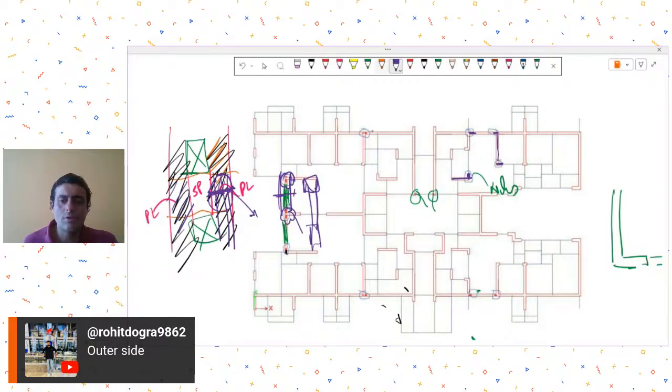Okay, so try that. And then over here, if these nibs are failing where the beam is connected, these generally fail due to the load transfer that happens from these beams to these nibs. So check what type of system you are trying to achieve, let's say in the x direction and in the y direction. Because you have so many walls, probably you want to go with an RCC structural wall system, and you're not relying on the beam framing to transfer much of the loads.